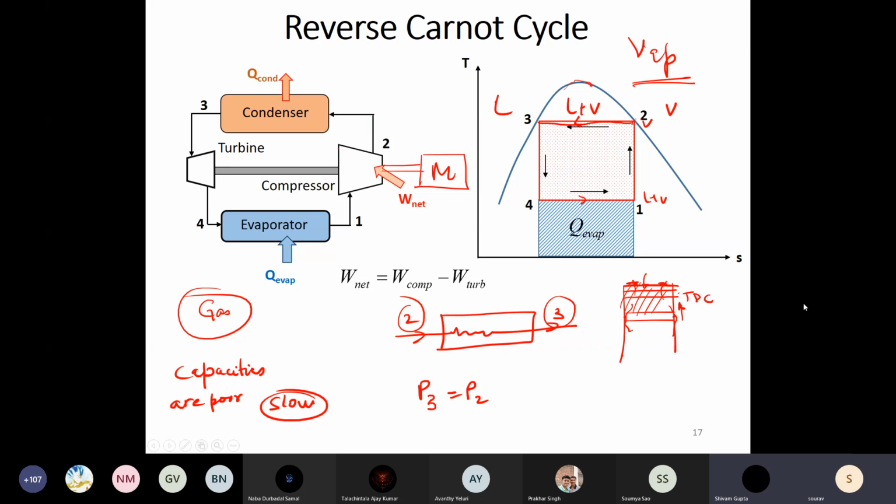Okay, but that doesn't mean that you do not have a hand pump. It is just that hand pumps will operate with much larger clearance volume. So you will not get such large compression ratios in the case of a liquid pumping device. So you have reciprocating pumps for liquid. It is just that they are designed with larger clearance volumes.